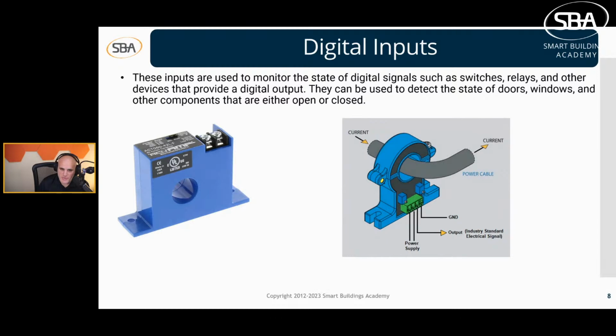A current sensing relay would enable us to go, and I realize this is a current transducer with a 4 to 20 output, but ignore that. It was the best image I could find. So a current sensing relay would sense current and then would close contacts based on that current to give status. And then you can actually set the current on that current sensing relay to a low enough current, or to a high enough...